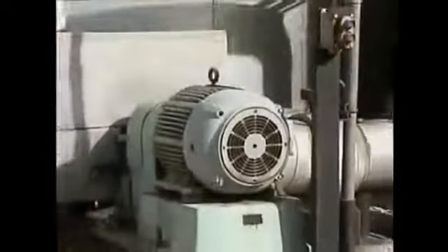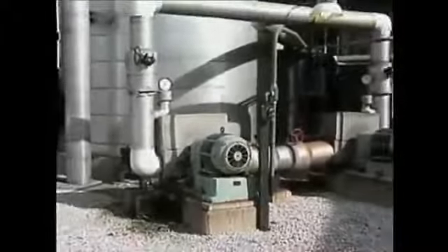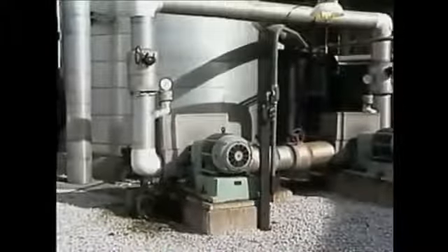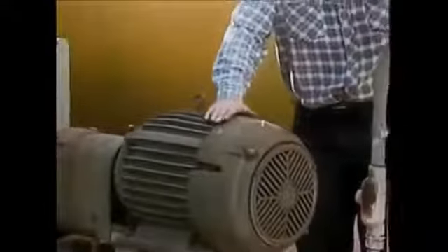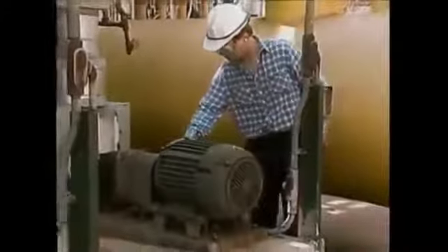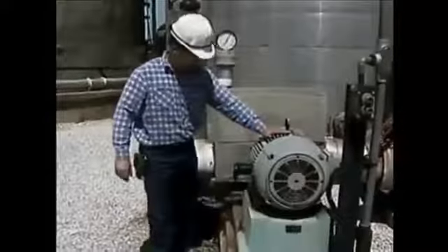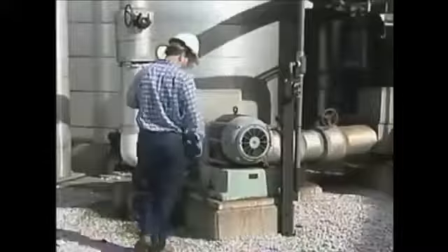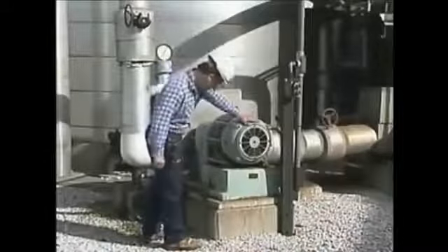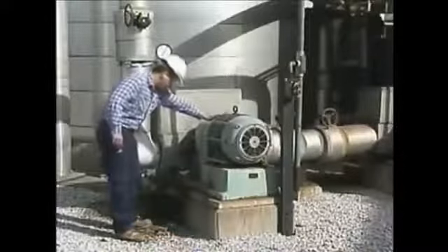Motors get hot during operation, and they may overheat for several reasons. For example, an overload may result when an excessive load is placed on the motor. You can carefully feel the motor casing to determine if the motor is too hot. In general, if the casing is significantly hotter than it was during previous checks, there may be a problem. You may also be able to detect excessive vibration, which is another common motor problem, by carefully feeling the motor's casing. You should also look over the motor and the equipment it's driving for anything unusual, such as sparking or arcing, which could indicate a short or an open.